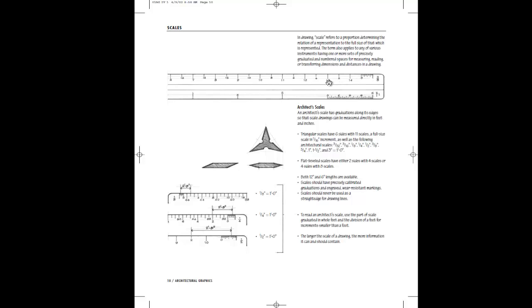So the 12 and the 13 will confuse you, but this is actually 5 read from the other direction, because 4 is here. So this would be 5 feet 0 inches if it went from the 0 to this line. If a line falls in between, what you do is you put the end of your line on one of these whole numbers so that the remainder falls within this range over here, and each of these would be 1 inch divisions. So there's 1, 2, 3, there's 3 inches, 4, 5, 6 inches, 7, 8, 9 inches, 10, 11, 12 inches.